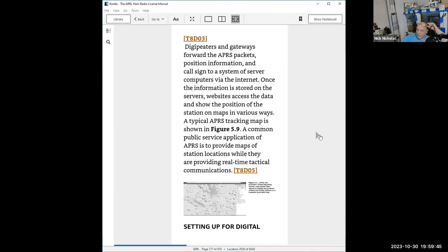And so that allows you the ability to track where your contacts are going. FT8 is another system that's also built around this concept, but FT8 generally does it manually. You enter where your location is when you set up FT8. APRS, automatic positioning reporting system, automatically, even when you move, when you travel, recalculates where you're at and keeps itself updated. It's a big difference. Okay.